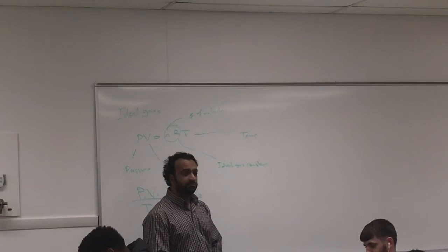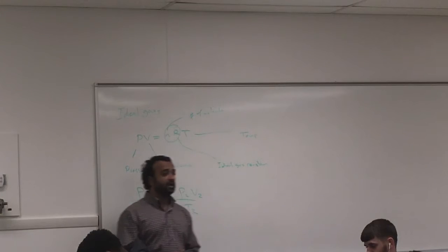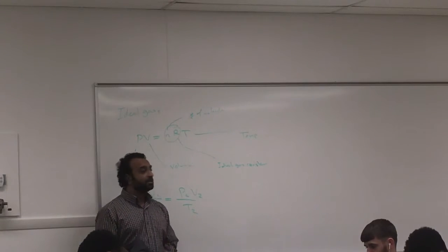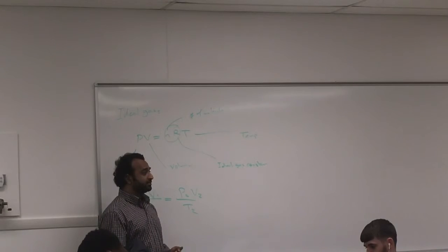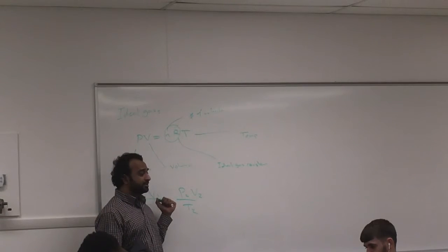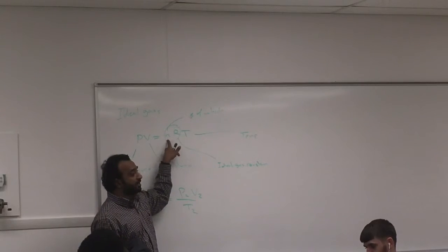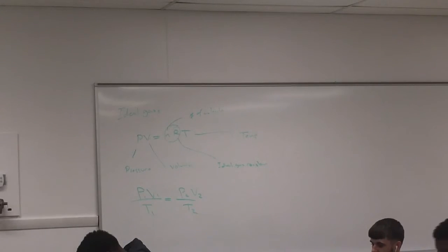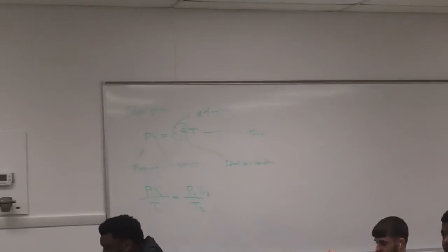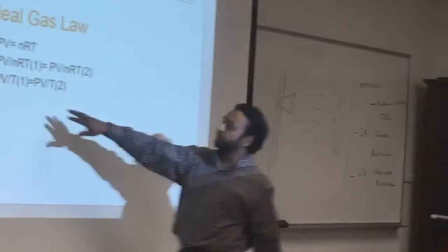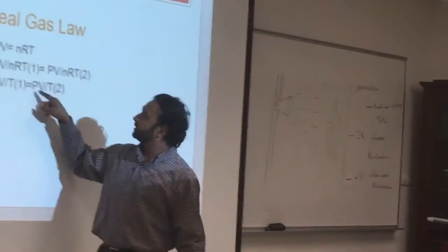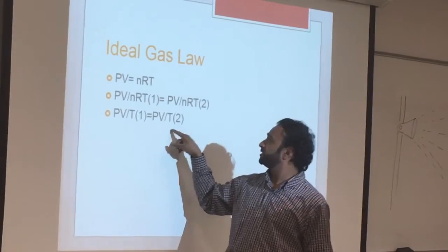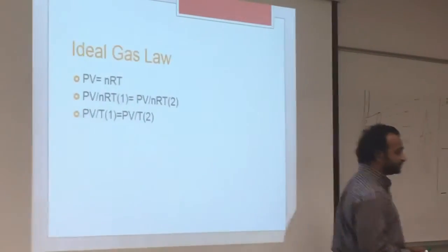Liquid does expand as well, but not as much as gas, and liquids do not compress. So when we try to pump gas into a boiler, we might run into the problem of compressing it, and you might not get the same amount of molecules in there. I'll do a few examples of that next class, and how we use that law, and that's exactly what you need to know: the pressure times the volume over the temperature at state 1 is equal to the pressure times the volume over the temperature at state 2.